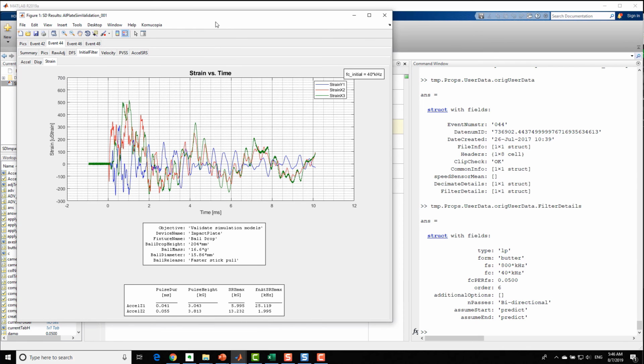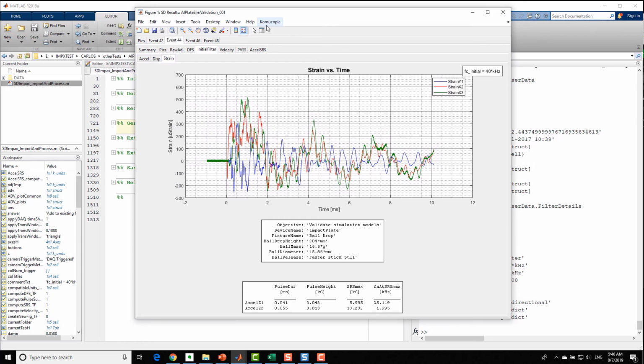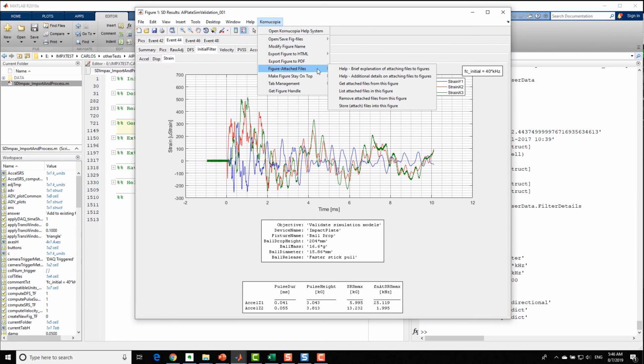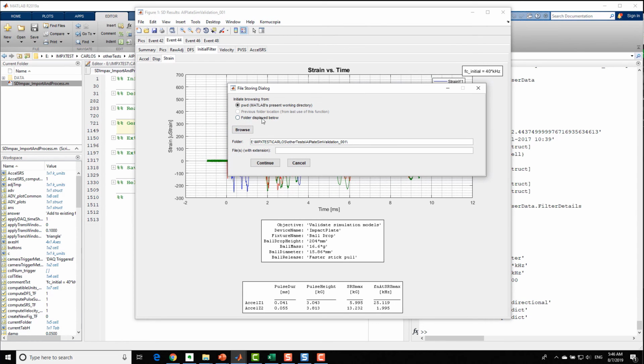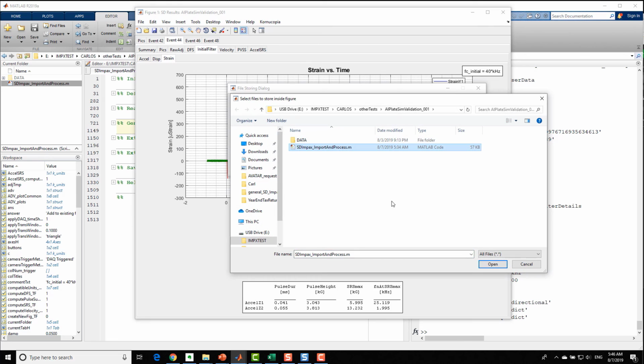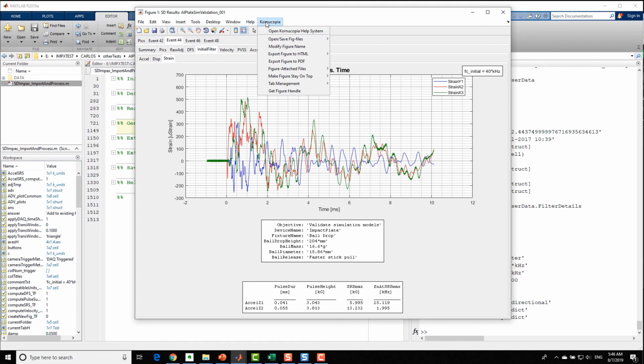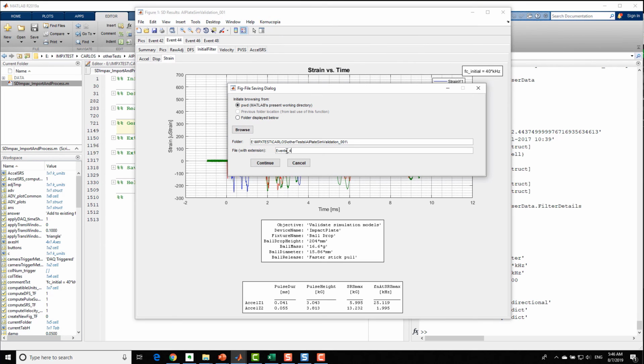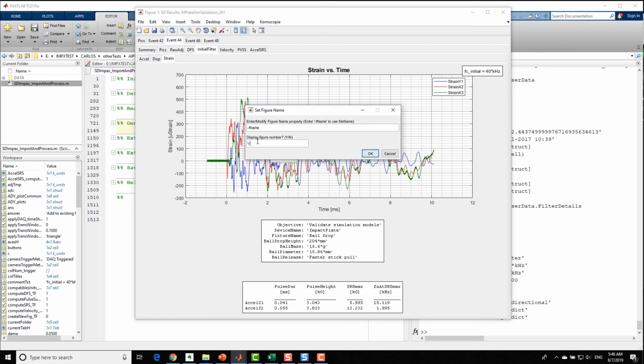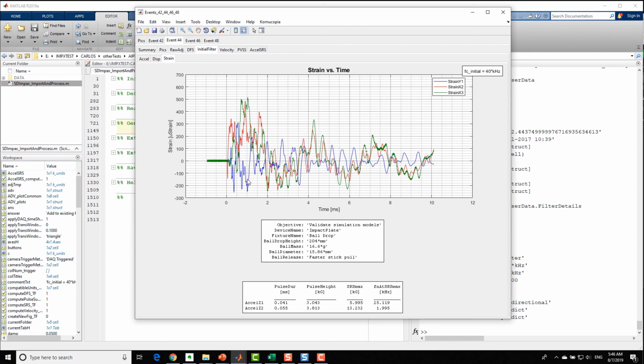Finally, we use the figure's Kornucopia menu to store the M script with the figure, and then use this menu to save the entire figure to a file, where all the advanced Kornucopia technology gets properly stored into the fig file. Remember, this fig file can be opened later in another session where all the results can be viewed in an orderly manner and any curves can easily be extracted for further analysis. You do not need the original source data for this to work because everything needed was stored in the fig file.